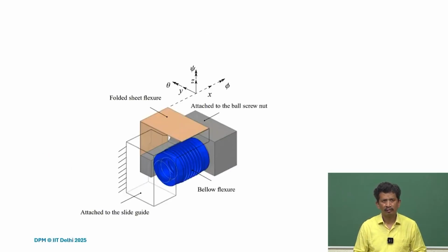What is normally done is we can stack the stages, translation and rotation, and directly connect them if we are not aware of degrees of freedom and constraints. But if you are exposed to these principles, very likely you are going to use them. So it looks like a normal setup, but then why not implement some of the concepts you have studied.